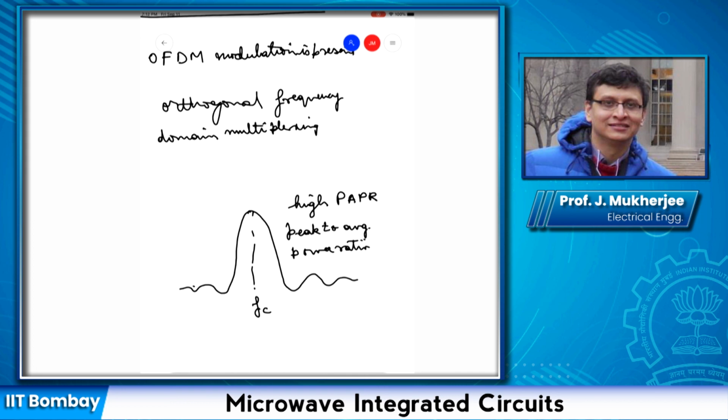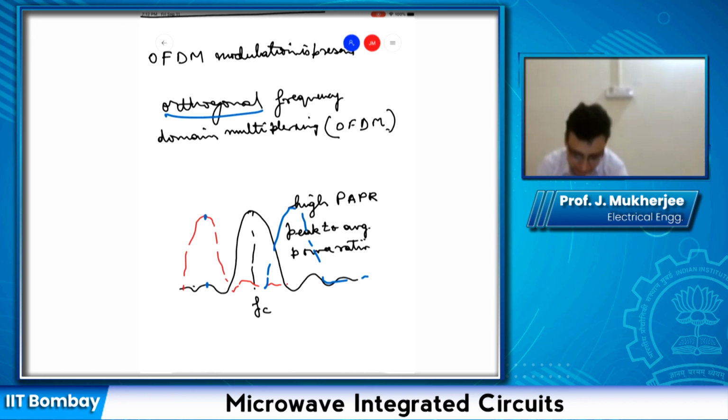Yeah, so coming back to OFDM, why it is called multiplexing is because in reality there are multiple such pulses present together, and each carries some information, and it's called orthogonal because the peak of any of these lobes corresponds to zero value of the side lobe. So at the peak value there is no interference from the side lobe. So that's one advantage.